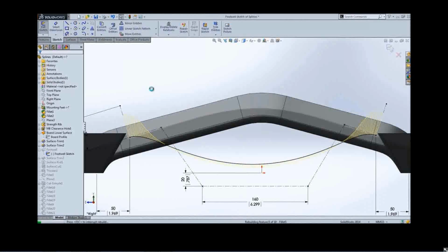There's a little bit of sketching in the style spline, but in a nutshell, what you're looking at here, this polygon around that spline, is the new way of drawing it. So you have to select style spline as opposed to using the traditional method. Great new way to make sure you get consistent curvature.